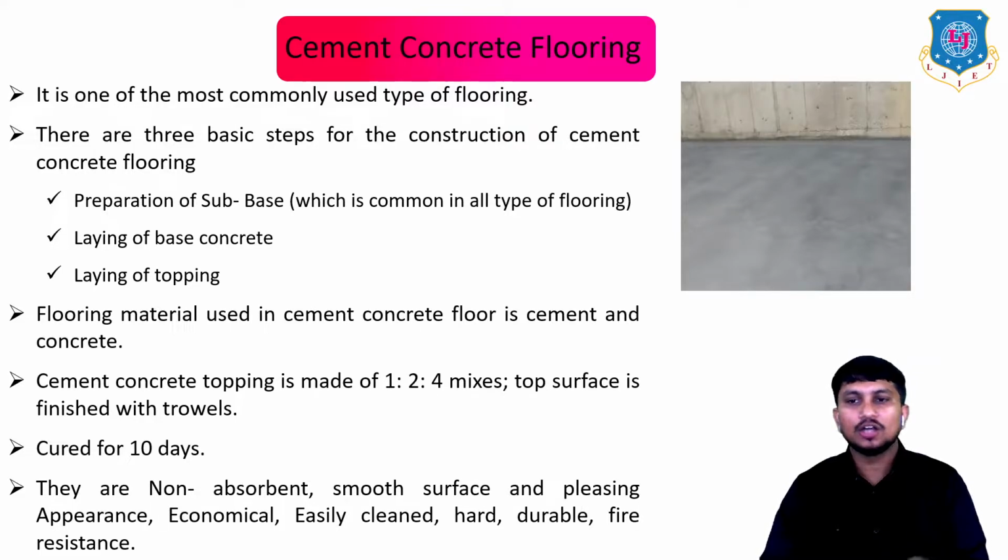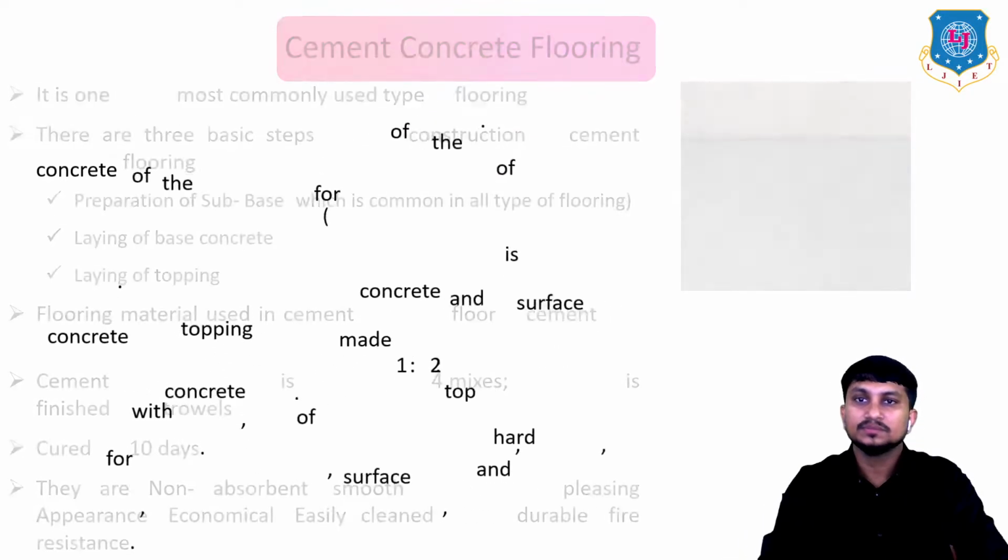Okay, it is then cured for 10 days. They are non-absorbent, smooth surface, and pleasing appearance. It is also economical, easily cleaned, hard, durable, and fire resistant. These are the various properties of cement concrete flooring.